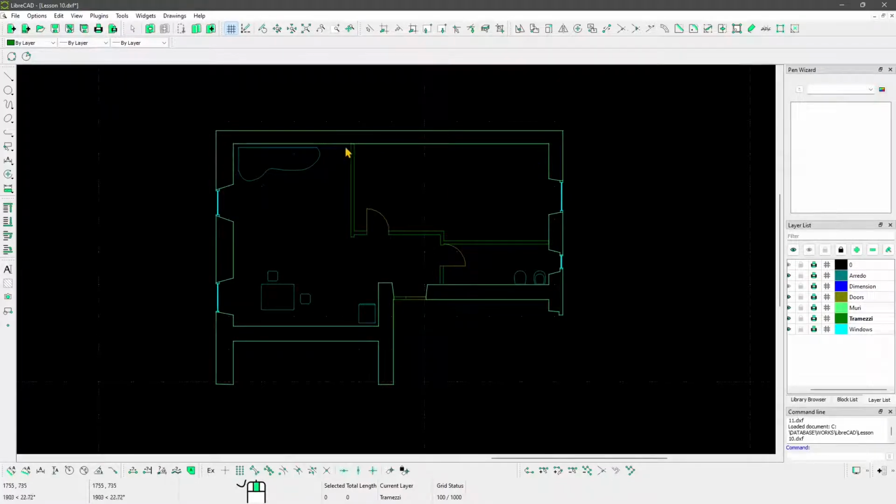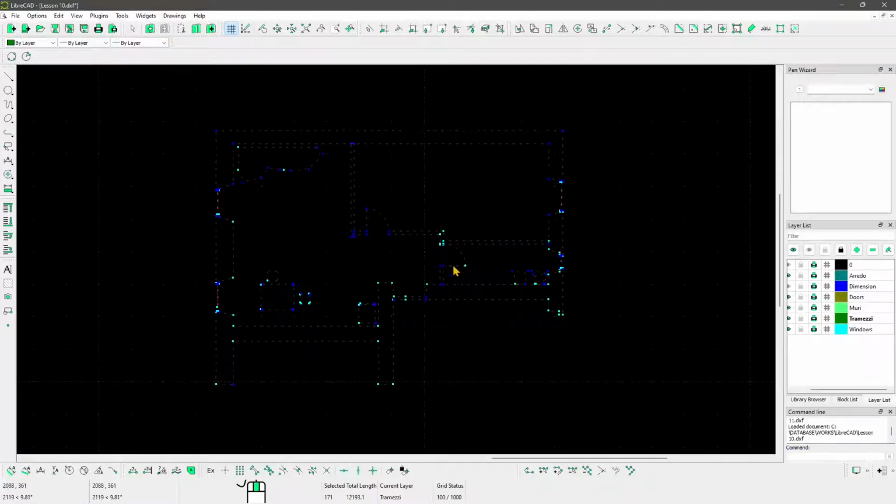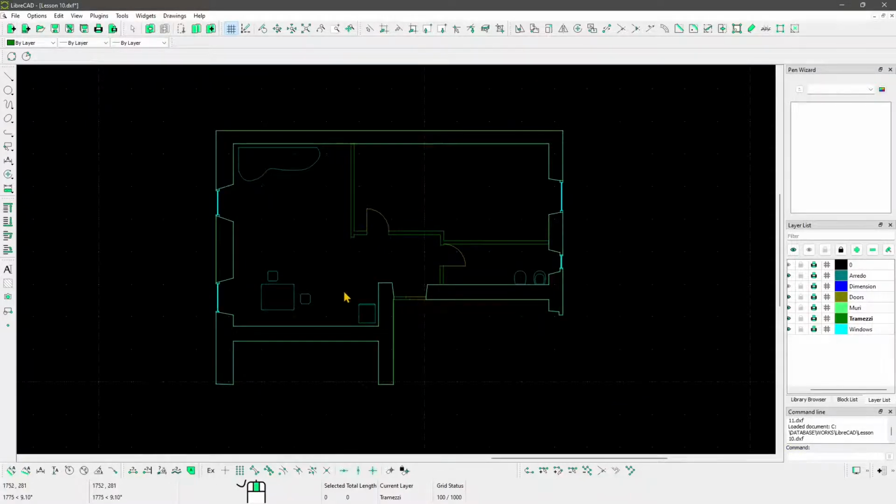So if you want to make your life easier, you can just scale these up, or I'm gonna leave it this way. This is centimeters right now because I want to show you then how you can adjust and fix that unit issue directly in Blender. So I'm gonna show you some tips and tricks in Blender just to start to create your 3D scene. Another really important thing is that everything should be polyline. Polyline will be better to handle, and in some software when you create a polyline, it's going to be extruded already as a solid. This is not working at the moment in Blender, but we can then convert it to a solid, and again I'm going to show you how to do that.